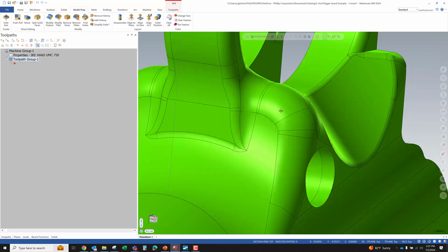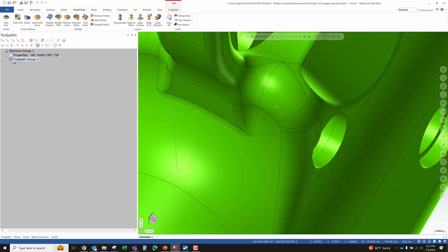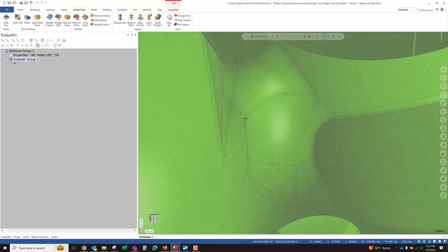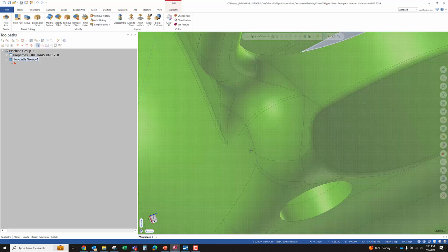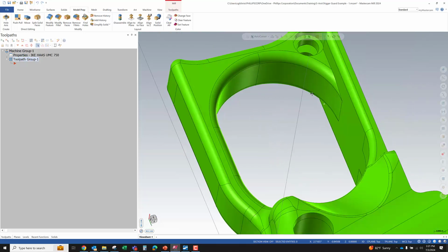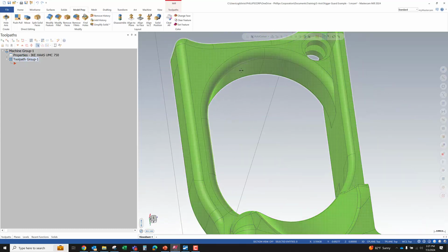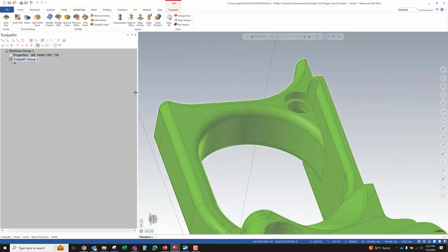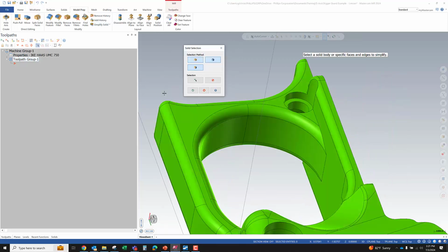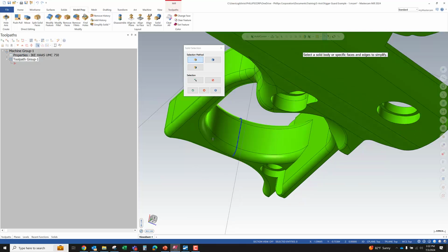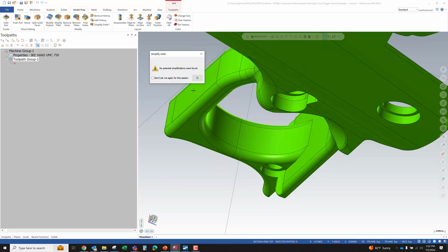Here we've got two different blends. The entire trigger guard, in my opinion. All of this? Yeah, okay, here's a good example, right? If this is the same radius, for example, we can go in here and do simplify solid. I'm going to have it selected for edge. I'm going to try to just simplify these edges. So I'll select them, say OK.